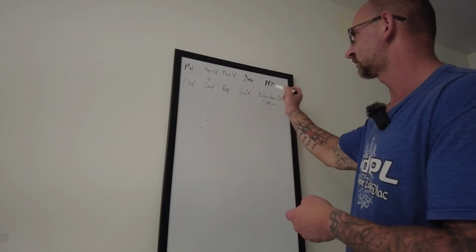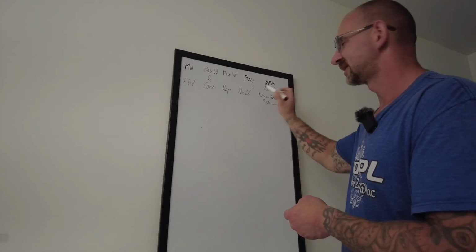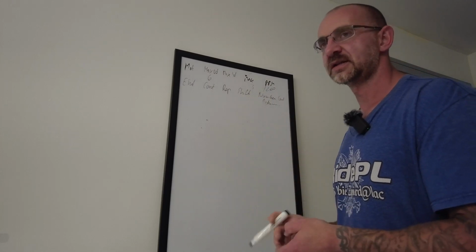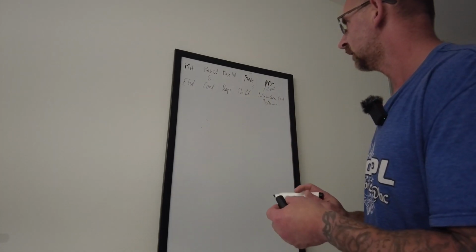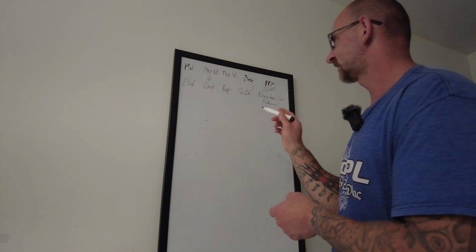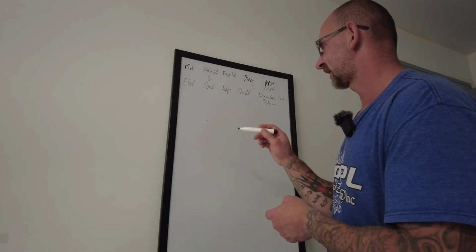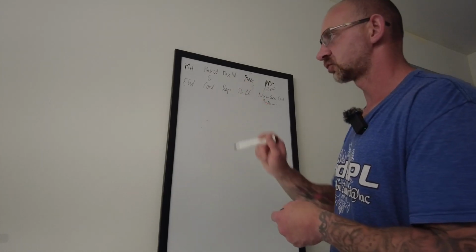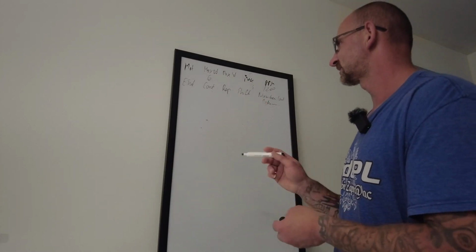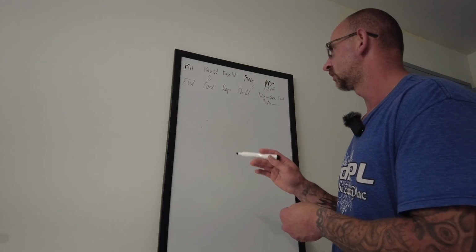So if you put, let's say, 1200, this is the max RPM it will do once you're in the center of the part. So material, max OD, clearance, retract. Like I said, if it's a lot of up and downs, then I would just shorten it to the size of the part. Max ID, always put as 0.